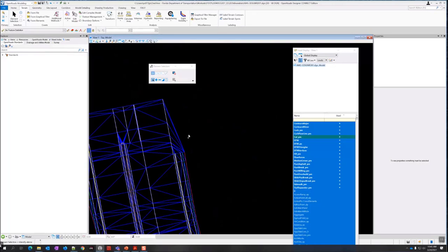If you still have extra triangles, you can delete some manually. However, we'll break any rules. So there is a rule to this, but it's probably not a huge issue because the break lines, we made these dumb break lines. They're not civil geometry. They don't have any rules anymore. So you're probably not going to be making changes to that without just recreating the break lines file. So it's probably not a huge issue in this particular case.